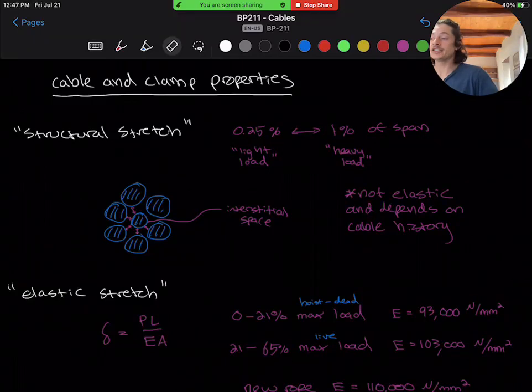The various engineered wire rope manuals discussed above have tables for total steel area, cable weight, cable strength properties, and cable stretch. Specifically, cable strength and stretch properties need to be adjusted based on their use conditions, and I'll discuss that below. These are the values you should be using during your design for cable properties, and they are in the EIA Bridge Binder, Volume 2 for design.